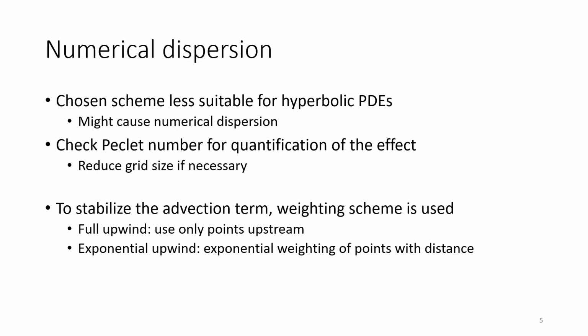There's also another method which is called exponential upwind. You can decide which of those two options you want depending on the flag you're setting. There it's not a pure upwind, but an exponential weighting of the points with distance. This is also something to try out to see which works better depending on the scenario you're testing. But the standard application is the full upwind, which probably is also recommendable in most cases.